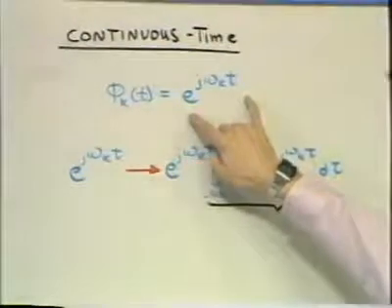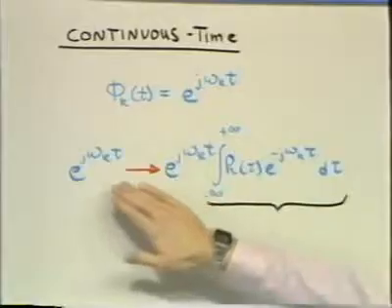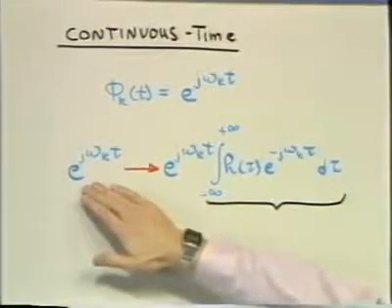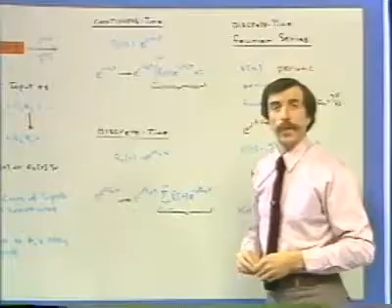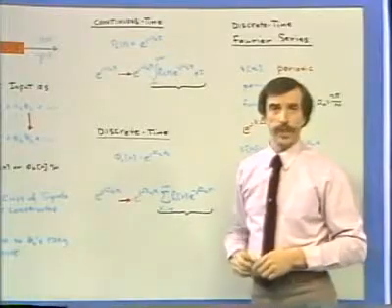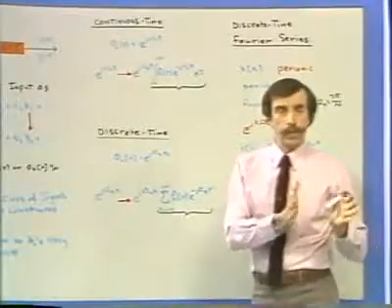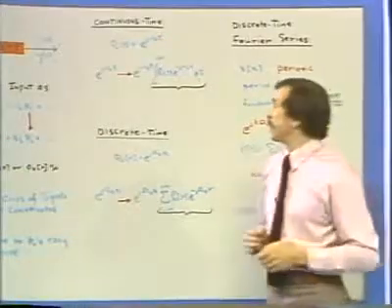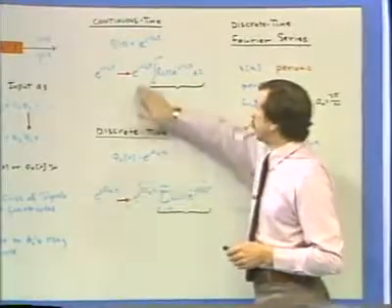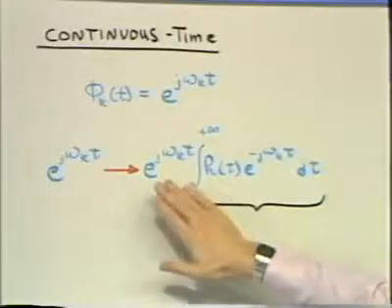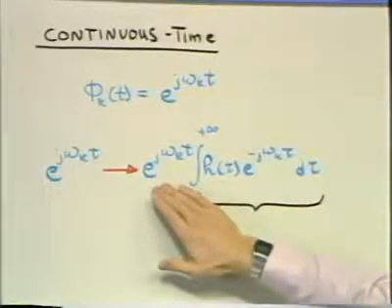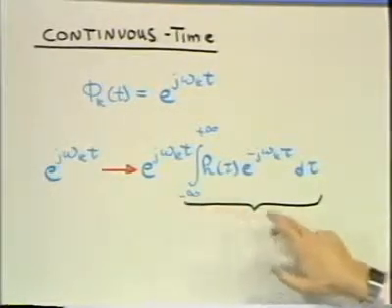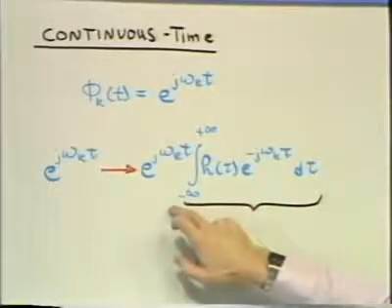The motivation there was the fact that the complex exponentials have what we refer to as the eigenfunction property, namely if we put complex exponentials into our continuous time systems, then the output is a complex exponential of the same form with only a change in complex amplitude.